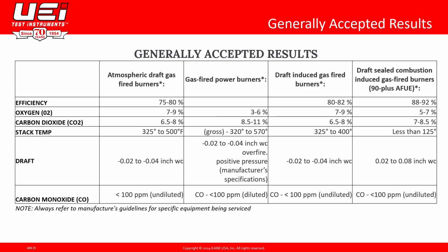And I want to say that no test is 100% conclusive. So this is just another tool in your tool bag that will allow you to know if you have a crack in the heat exchanger and further investigation is warranted. And here we can take a look at our generally accepted results. And by the way, these are also free to download. If you go to the ueitest.com website, you can download all of the generally accepted results. And again, I'm speaking in generally accepted results. Always defer to the original equipment manufacturer.